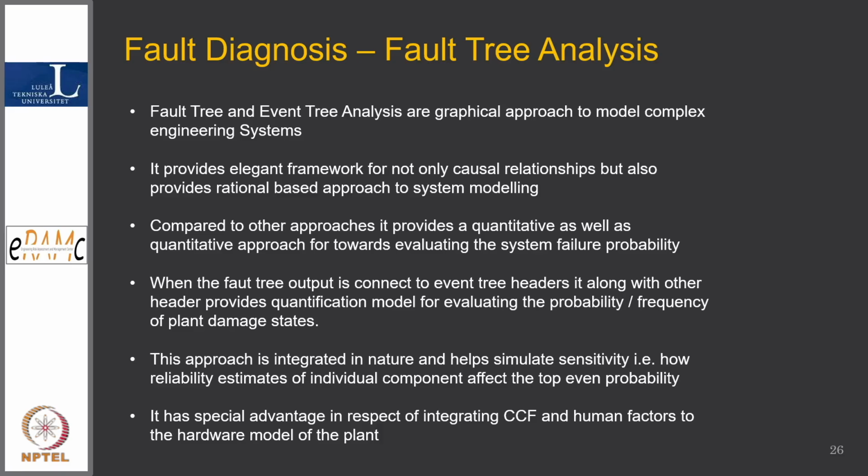Fault trees can take input on human factors also, and common cause failure also. It's not that there is no provision for handling common cause failure. The plants are built considering various methods of isolation and treatment of common cause failure, knowing a priori that these equipments can see a potential common cause failure because of environmental or ecosystem factors. Sometimes a distance factor, sometimes a separation factor, sometimes an elevation factor.